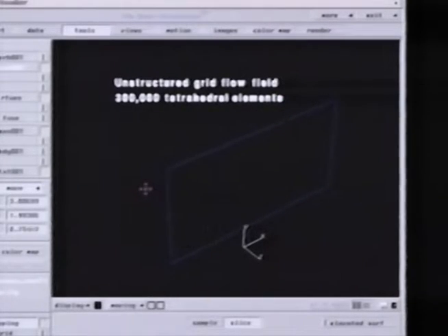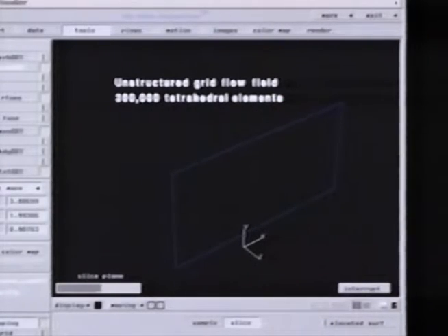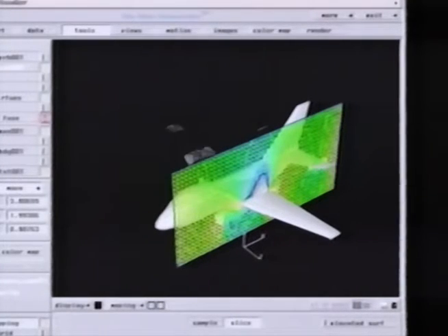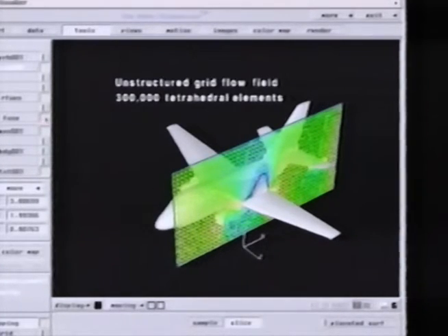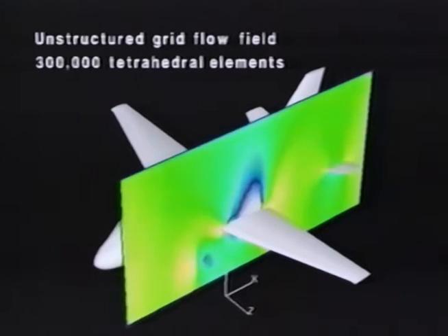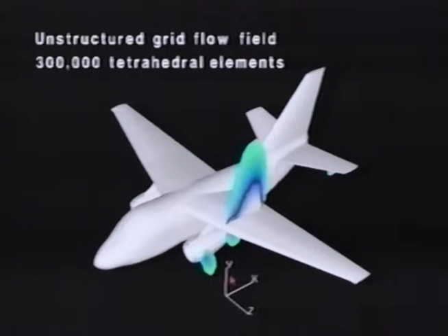By specifying simple display mode and enabling the Data Visualizer's computation status meter, we can get an idea of the true response time associated with interactive interrogation of this type of data set. To better bound this performance indicator, the airframe geometry contains approximately 36,000 polygons. The workstation being employed is of mid-level 3D graphics capability and contains 48 megabytes of physical memory. Display options for the cutting plane parallel those of previous tools. They include a shaded mode, a thresholding capability, plane boundary toggle, and contour line mode.